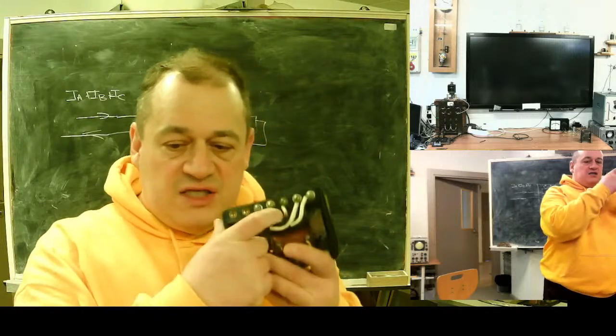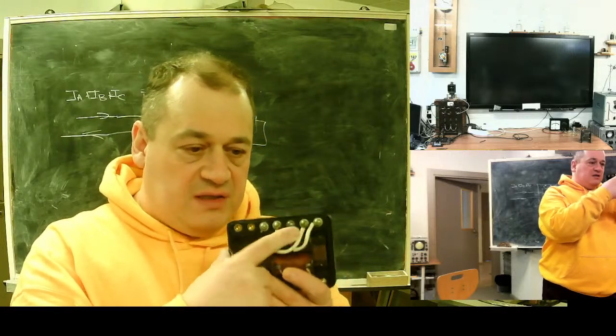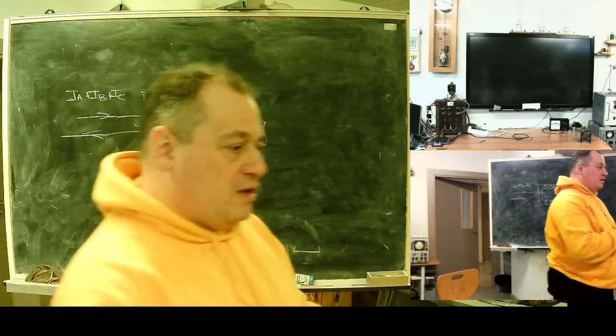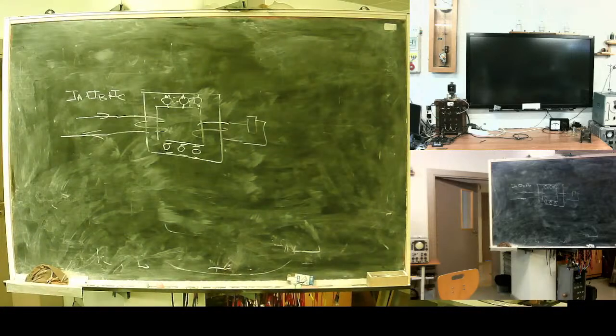It's for high currents. It should withstand 200 amps, this winding. This one is for the sensitive relay. It's a special saturatable transformer. In case of low current, this area, where only half of steel, works as usual, and at small current it's a simple transformer. At high current, this area saturates and secondary current will be limited. Current limiting transformer for earth fault protection.